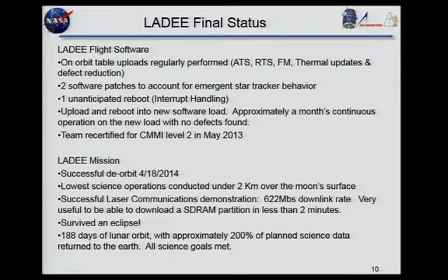So we also had one unanticipated reboot. We were running the laser communications device, and just when we finished sending down one of our SD-RAM partitions, what you had to do to fill up its queue was send down whole SD-RAM partitions. There's an interrupt at the end of that send, and inadvertently we had a task lock in the middle of an interrupt service layer. Very, very difficult to find. Our V&V system didn't find it. Our inspection system didn't find it. But of course, the LaserCom found it.